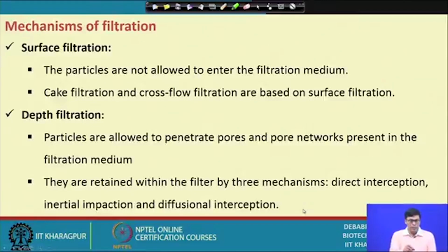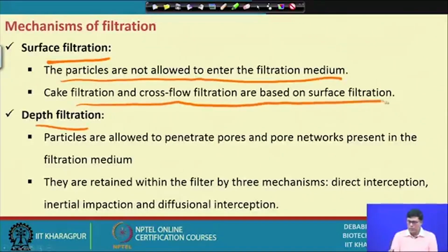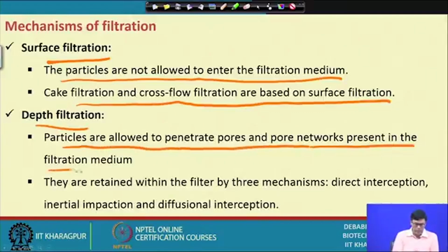Now we have different mechanisms of filtration: surface filtration and depth filtration. In surface filtration, particles are not allowed to enter the filter media, as I have already shown you, and cake filtration or cross flow filtration are based on surface filtration. But in depth filtration, particles are allowed to penetrate the pores and pore network present in the filtration media.